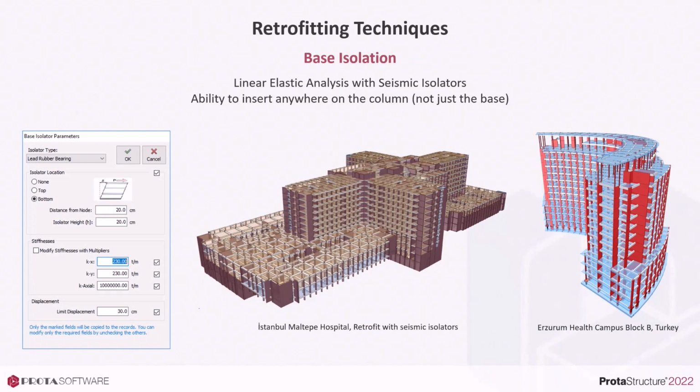Base isolators can be used as a retrofit technique as well as a brand new design strategy against seismic excitations. Base isolators simply concentrate the lateral deformation at a relatively soft isolation layer. They also elongate the vibration period of the building so that less spectral accelerations are experienced. However, soil conditions must be carefully investigated for a possible resonance situation. Besides, the isolators introduce additional damping to the superstructure accelerations, and they help reduce the relative drifts in the upper structure, allowing an almost rigid body oscillation.